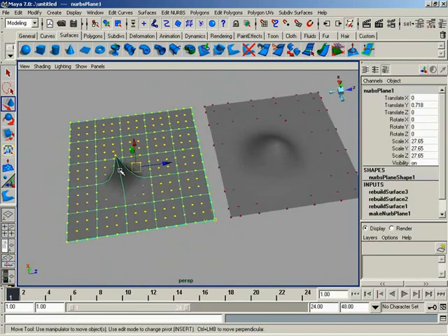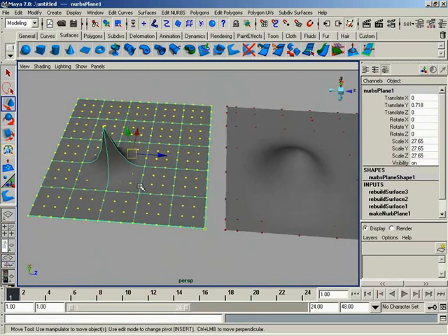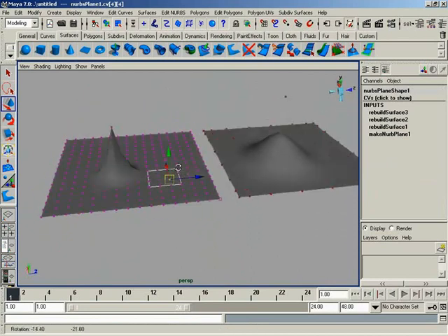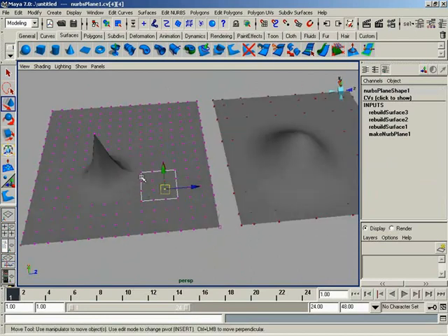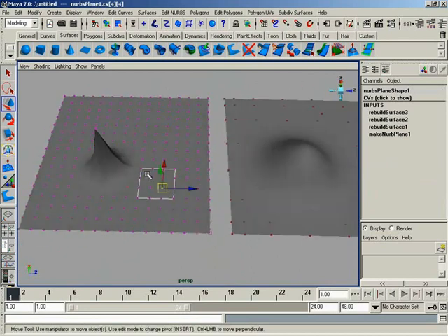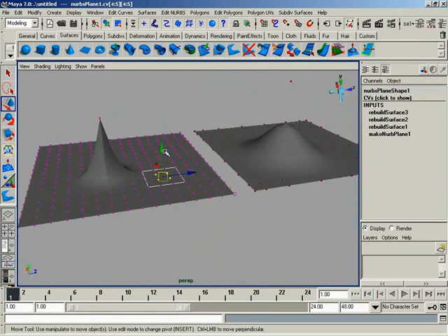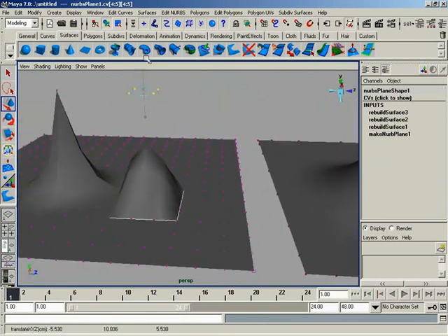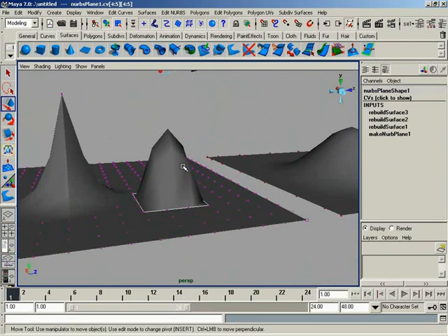And that is because each of these panels is, in a sense, calculated separately of the others. In fact, if you grab a control vertex, you can see in your area of effect, you're only affecting inside this area. So I can grab just these 4 CVs, pull them up, and notice it has no change whatsoever over any of the other objects.